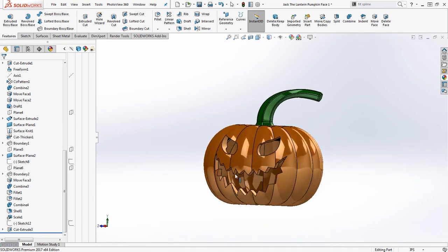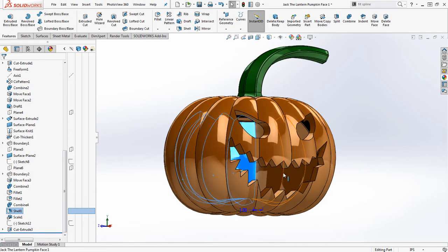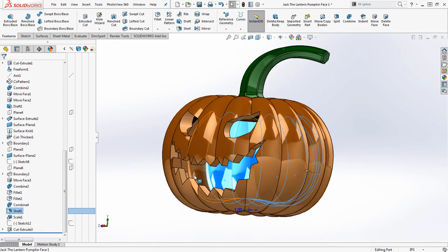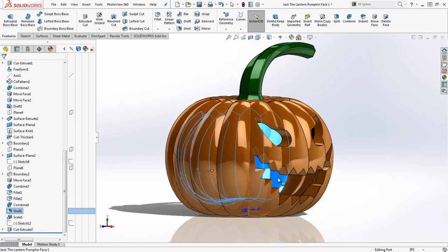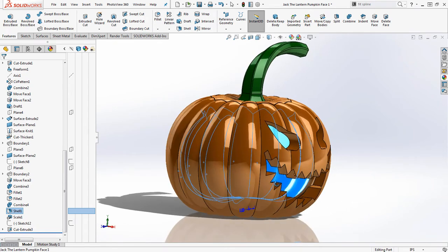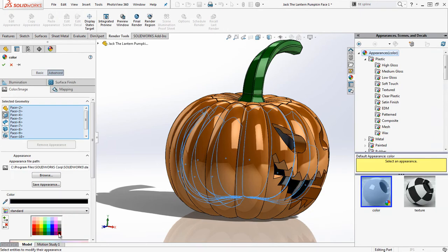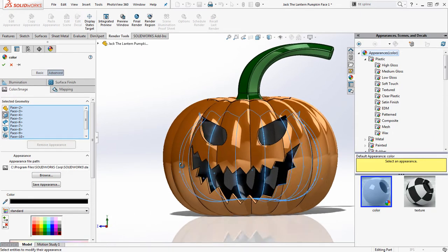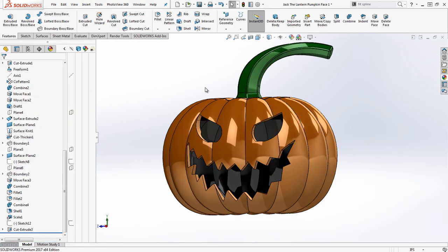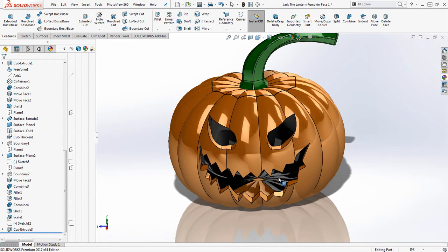Now for the faces in the back, we can also do similar. We're going to leave a little bit of reflectiveness on these. And once again, we'll choose Face. I'll choose black. And you can see right now, if you just clicked OK, this is going to be pretty reflective, which wouldn't be really all that helpful in a rendering.